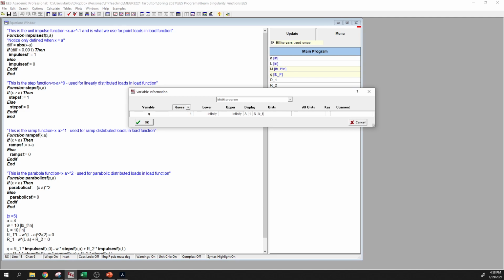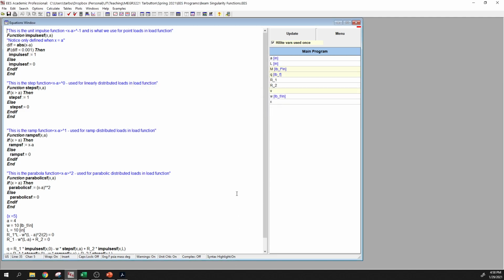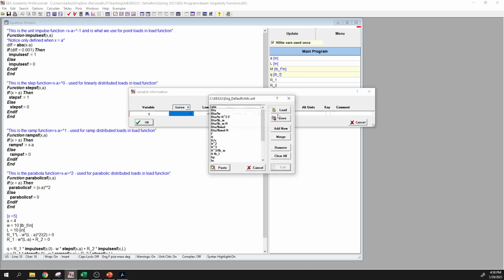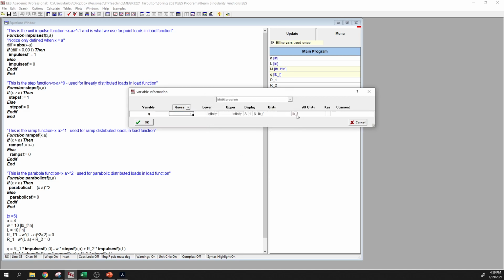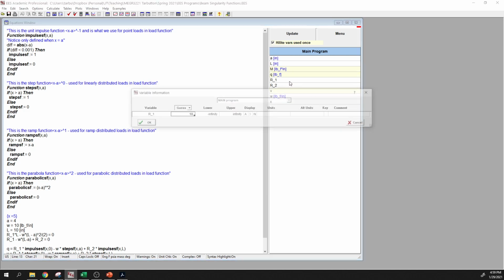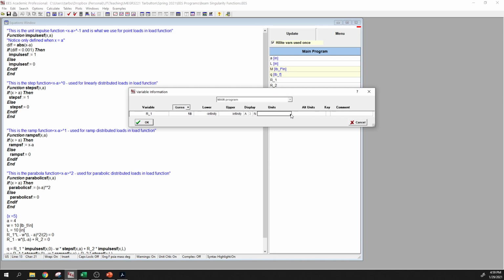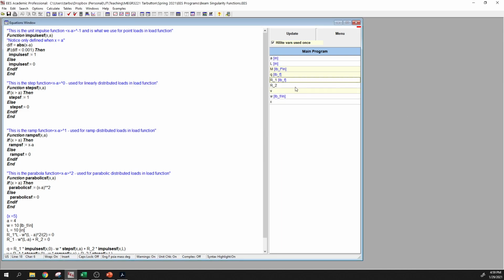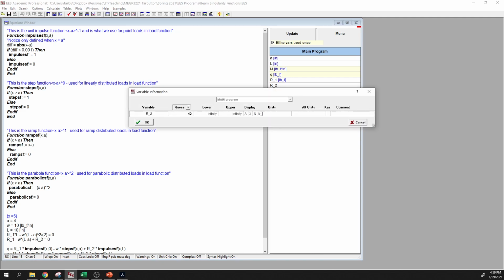And if you don't know which units to pick, instead of just blindly doing it, you can right-click here, and then it'll bring up the units for that system. In this case, I changed it to the English system, so we can use this here, and you can just paste it in, and it'll paste the value in. Okay. All right. So we have LBF. Our reaction forces are actually also in pounds force. So we can enter those in.